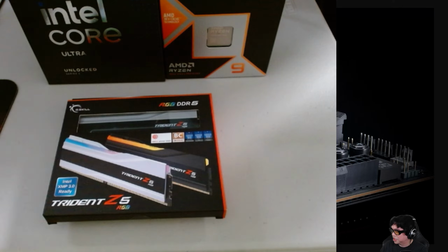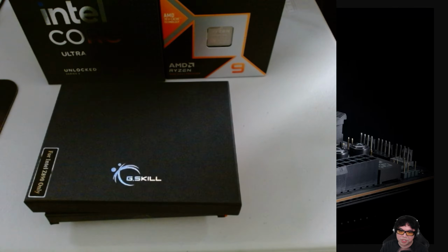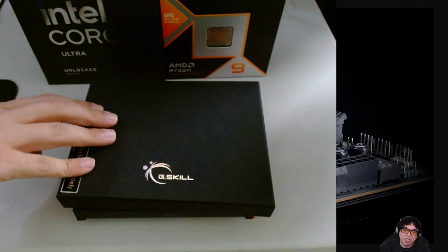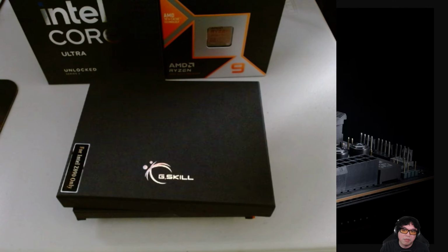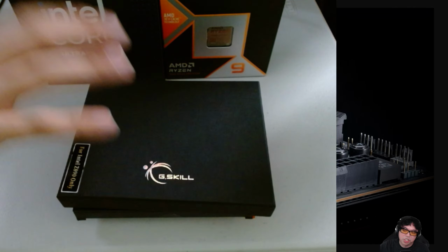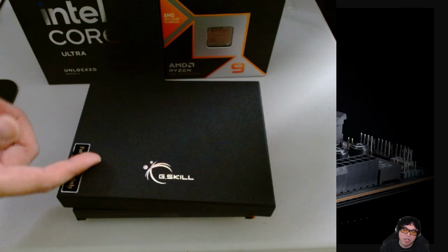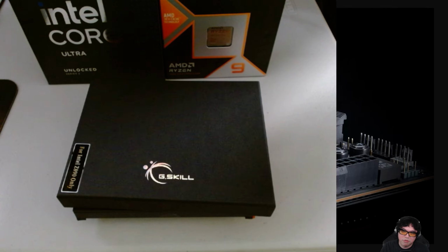So we are going to test this in the Intel platform, assuming I can get the 4 sticks to work. We'll also test it in the AMD platform. So for those of you that are wondering about AMD, the CKD does not work with the AMD memory controller currently. Now the kit will work, it just will work like regular UDIMM. The clock driver on the PCB of the RAM will basically be passive. It won't do anything. It'll run in something called bypass mode. And what that means is it'll just function like regular UDIMM memory at that point.